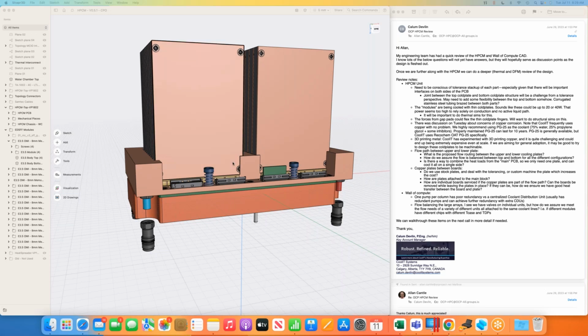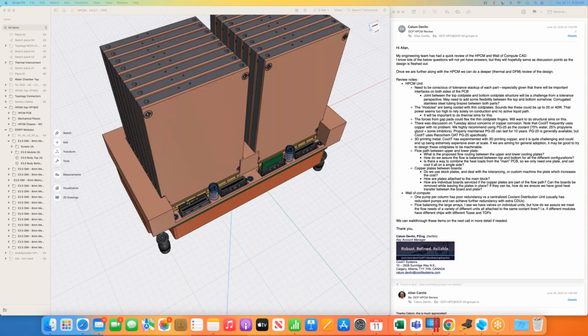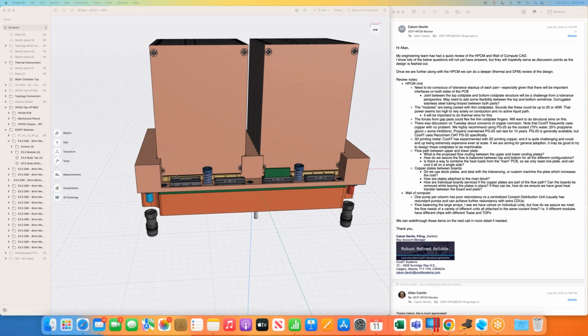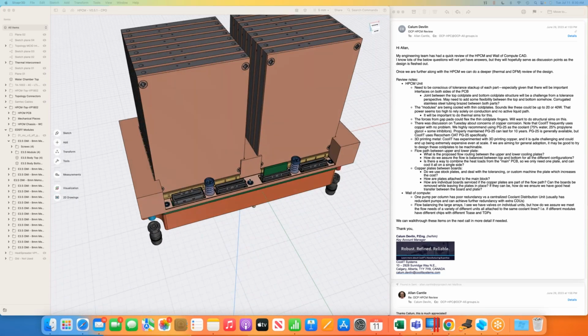So I guess in terms of issues, we've got the thermal management. This was one we've highlighted for everybody that wasn't on previous calls: can we actually thermally cool a 25 watt or 40 watt E3 module with this novel heat conductive approach? We're thermally simulating that. I'd also like to build something where we can actually physically test this, but we've got simulations going on at the moment.